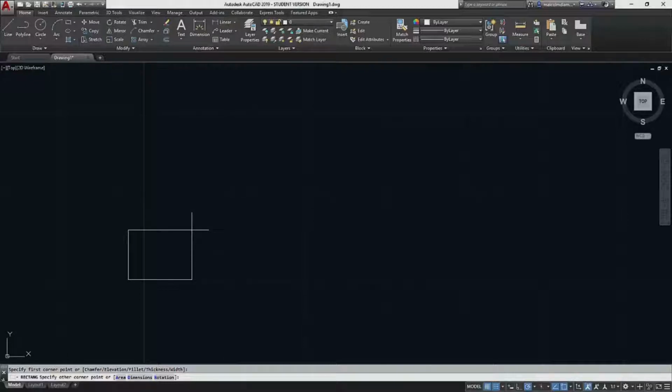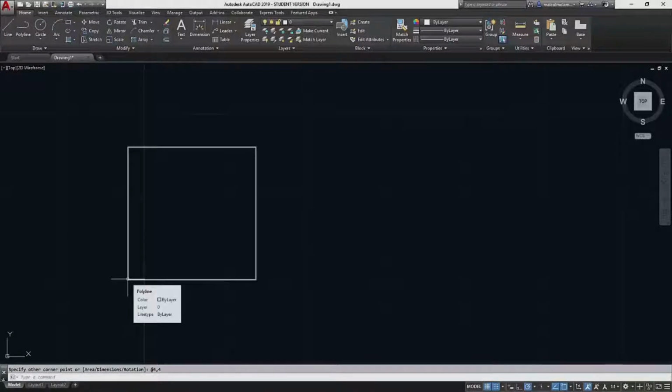However, what we need to do is to use what you call an incremental command. So we do Shift and 2, gives you the @ sign, then 4, 4, and enter. That too will put a 4x4 cube on there. It doesn't matter if you got the grid on or not, because we picked a point. With the @ sign, it says go to incremental.